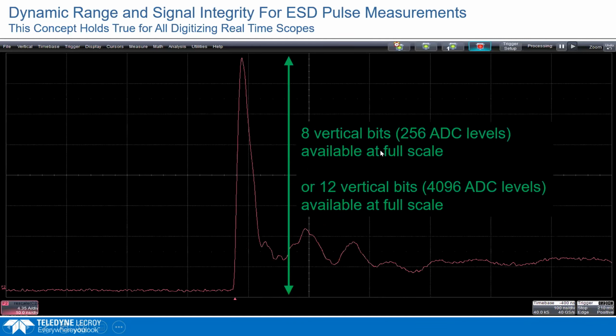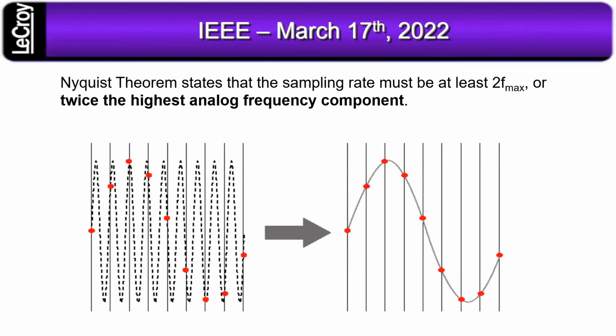So that's a quick overview of something that actually happened, a war story from testing with an oscilloscope. I wanted to share that because it turned out that it's necessary to have about a 250,000 to 1 oversampling on the fundamental frequency of that EFT signal in order to correctly represent it.